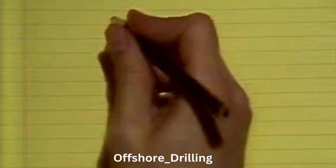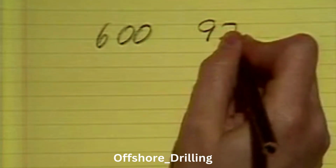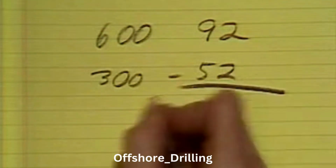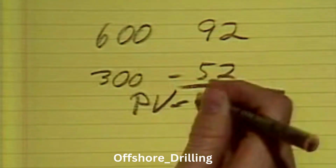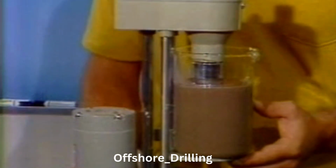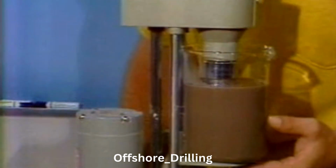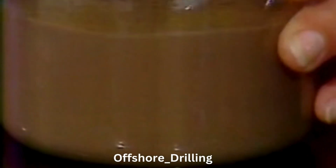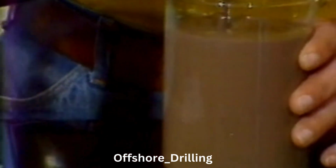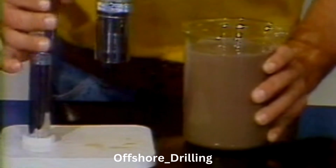Here's an example. If your 600 RPM reading is 92 and your 300 RPM reading is 52, then your plastic viscosity, your PV, is 40. You can see that this measurement is a lot more scientific than your marsh funnel. Keep in mind that this measurement is strictly a resistance to flow caused by mechanical friction, particles bumping against each other. There's more to viscosity than that.